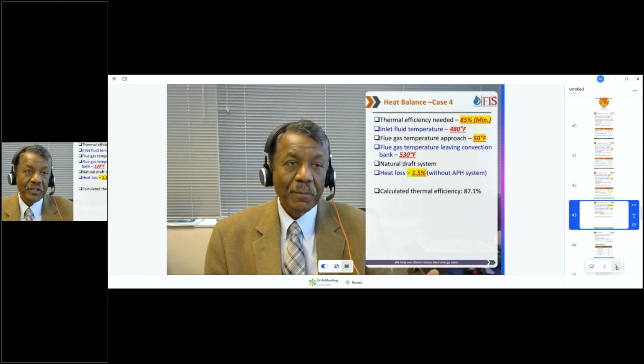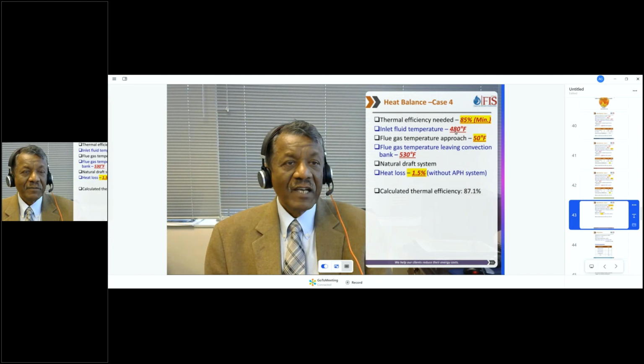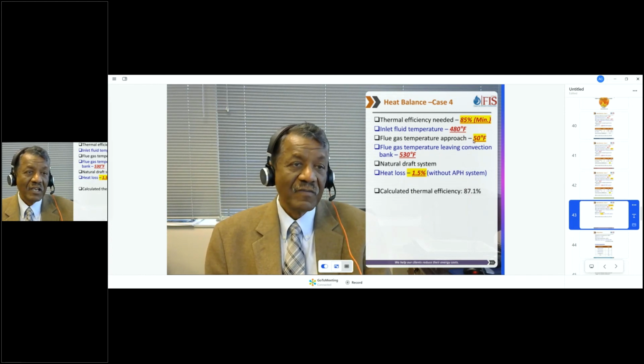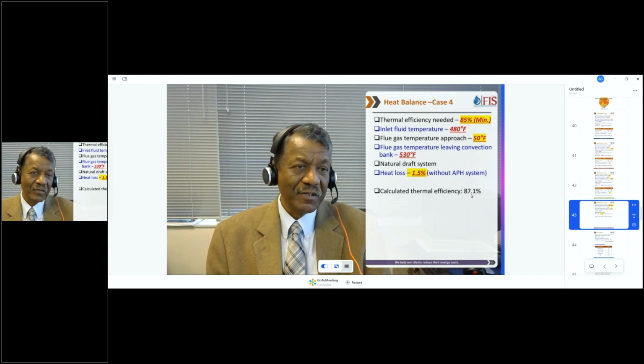This is another option where the minimum efficiency specified is not 90%, but 85%. So with 85%, I said, okay, I don't need to put in an air preheater. I put an inlet temperature of 480. I put a 50-degree approach, and when I put a 50-degree approach, I get 530 degrees. And with 1.5% heat loss, I'm able to get about 87%.